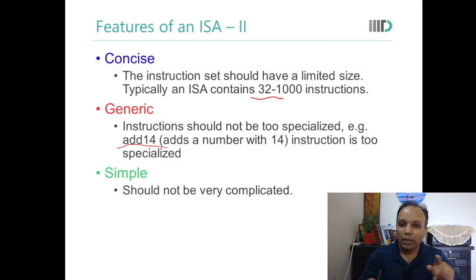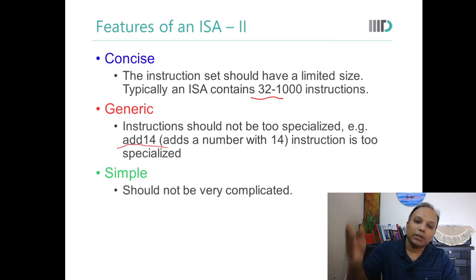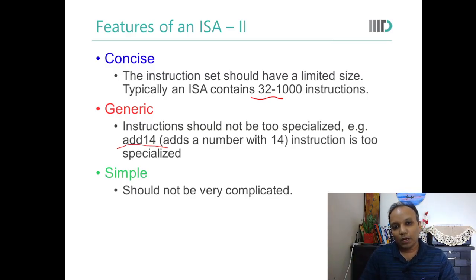That is why I want to again highlight that CISC has a relatively more complicated ISA compared to RISC, and that is why you saw in that plot where we plotted the processor performance trend, when RISC was introduced, the processor performance steadily increased significantly. Because of the simplicity of the ISA in RISC, you can really optimize your hardware much better compared to a CISC processor. So, this is very important.